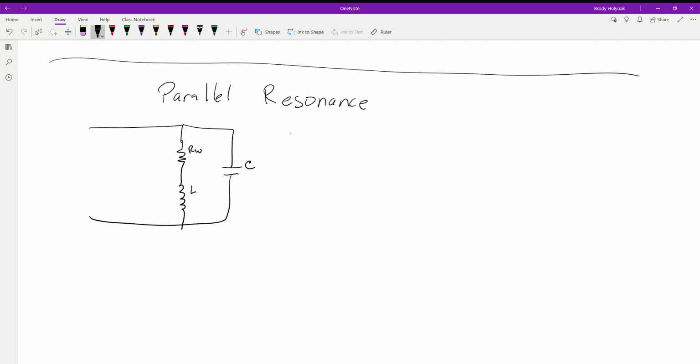Plus, this is also going to make this circuit a lot easier to solve when it comes to calculating the total impedance and a couple of other things, because it's going to separate everything out into just our plus and minus 90 degree angles and our 0 degree angles, which we can quickly convert between polar and rectangular notation.